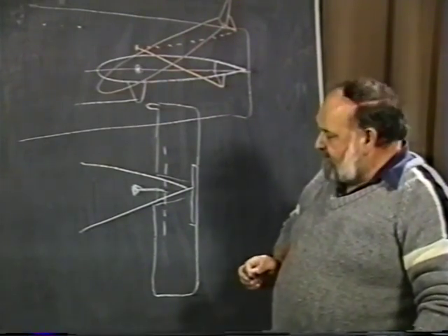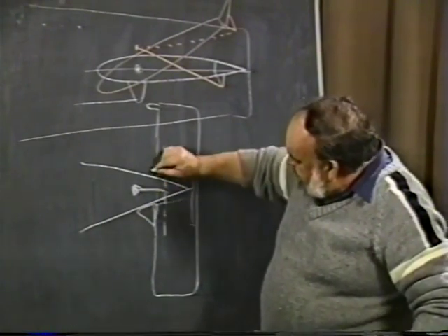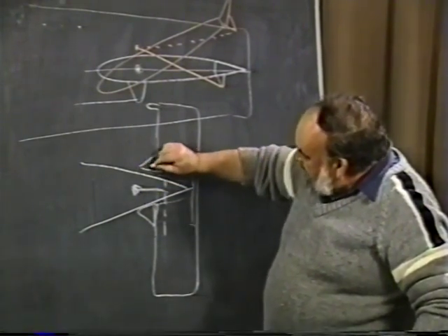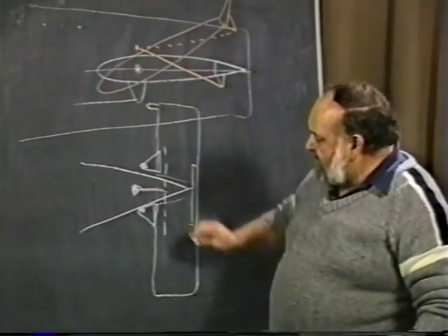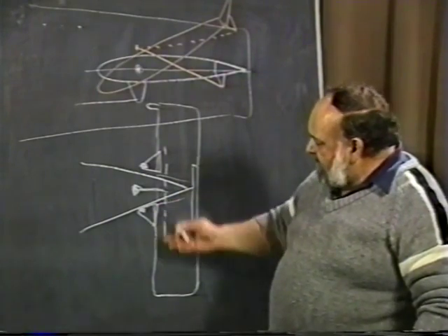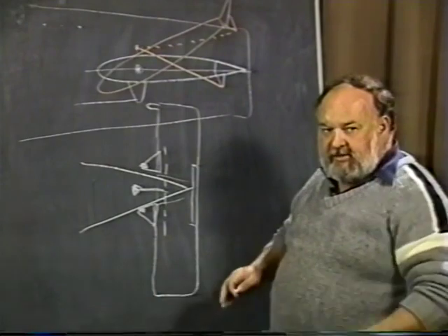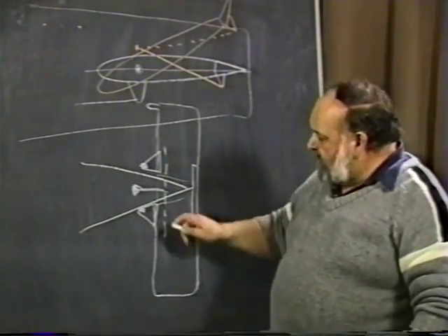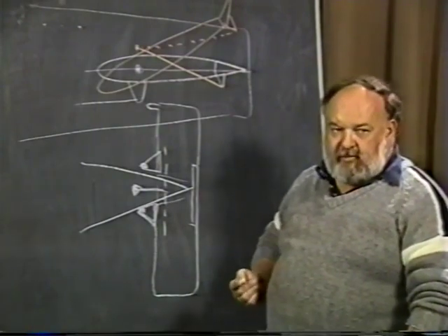One of the ways we came up with, though, is why not build little surfaces out here like this and put the lead on that. Now this did two things. One, it got us the lead further out from the leading edge. It put some on both surfaces so it balanced the thing so that it was torsionally pretty nice and stable. But most important, it gave us that aerodynamic characteristic of a little delta wing or swept wing surface in here.